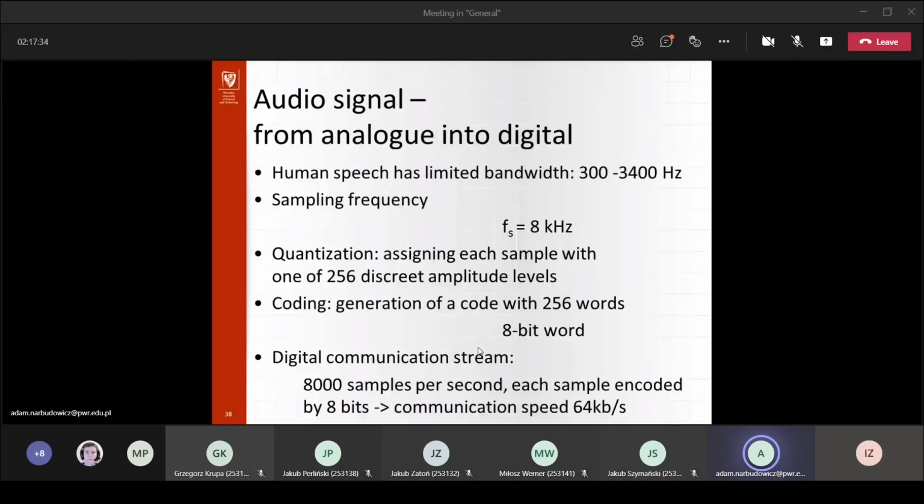Okay. So bear in mind here that this is actually signal really before it enters channel coding, right? So typically the 64 kilobits per second, that's just for transmission of your signal. If you want to add some redundancy, for instance, single bit parity check, the simplest one, this would change from 8 bits to 9 bits, okay? Which would correspondingly change your calculation over here.